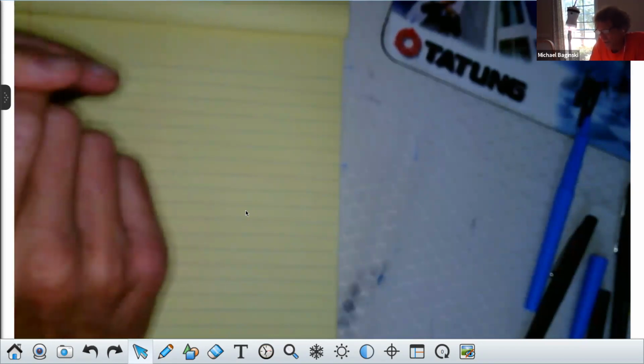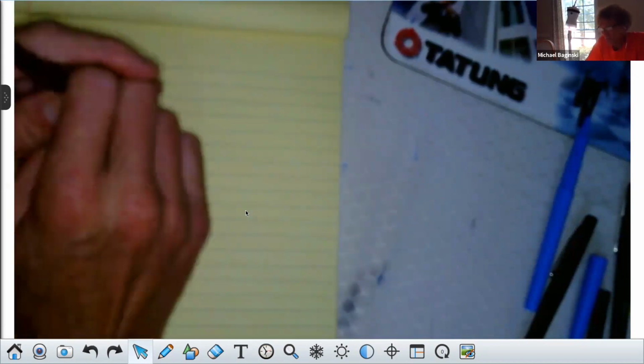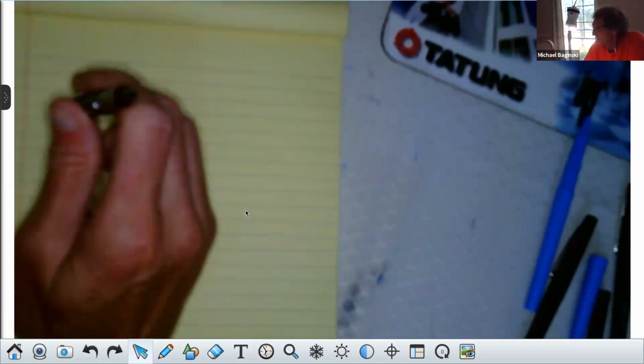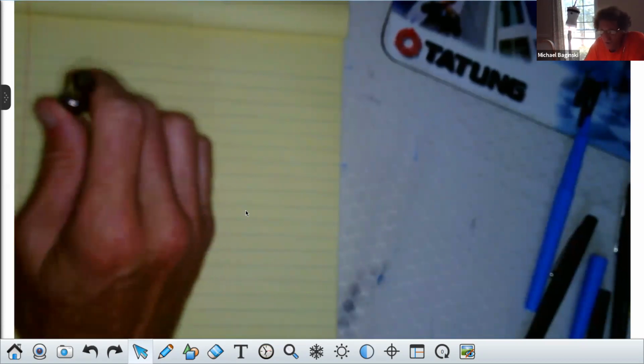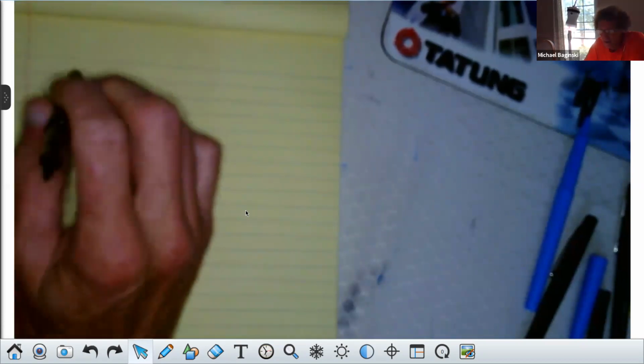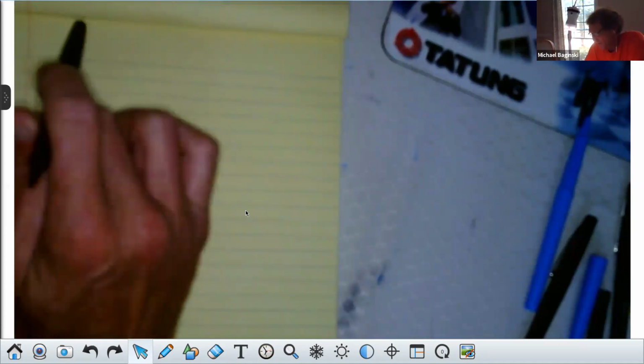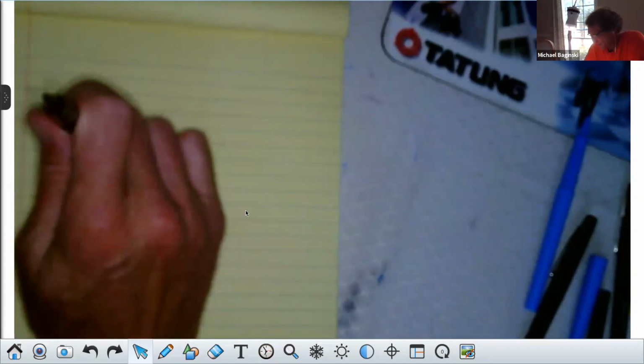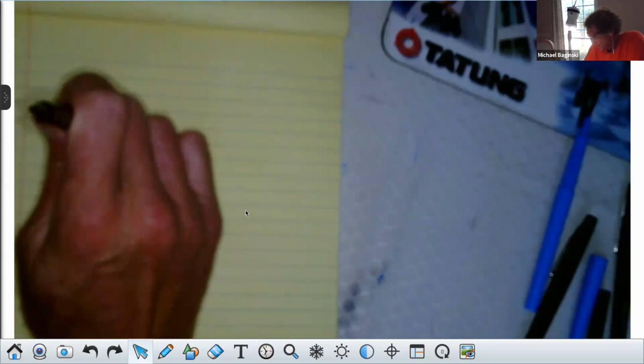All right. And when you put something up there, there's a lot of reasons for this, but basically what you're doing is giving any DC potential a direct short. And basically that inductor will act like a fuse and blow up. And I'm not going to get into the reason there's the DC offset sometimes, but there is. And you'll see only capacitors used in parallel, to correct the power factor.